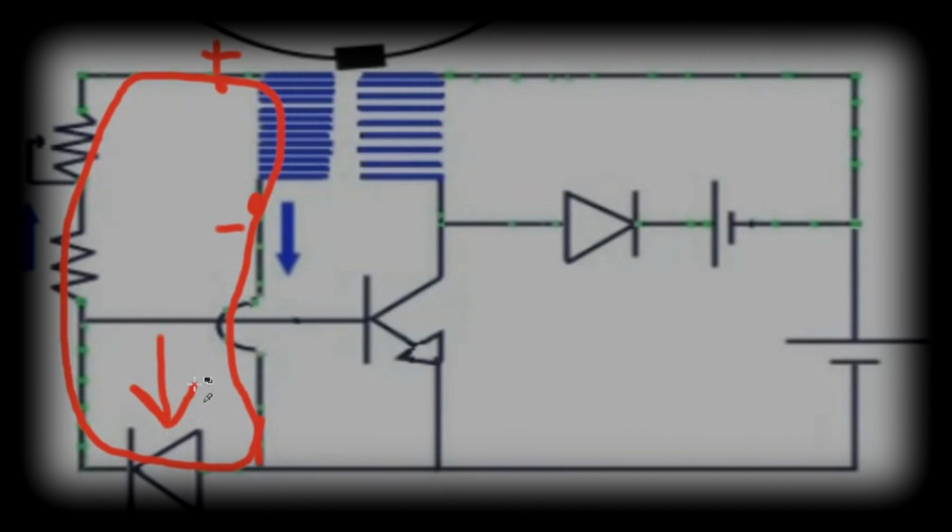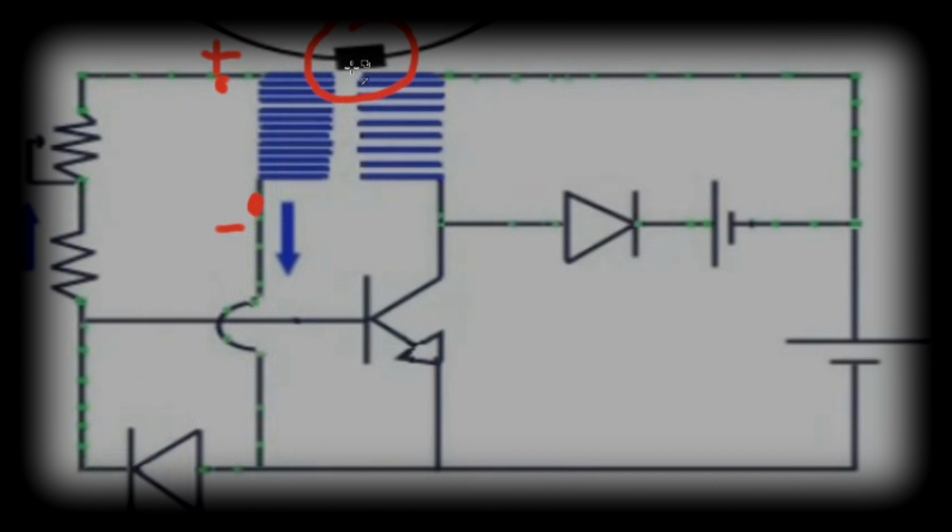So any analog signal or AC signal from a rotor magnet that hits the trigger winding will produce analog current with a pulse of north-south pulse, which is analog AC. North-south from the rotor magnet. This diode is the clipping diode to clip the AC, make it DC.